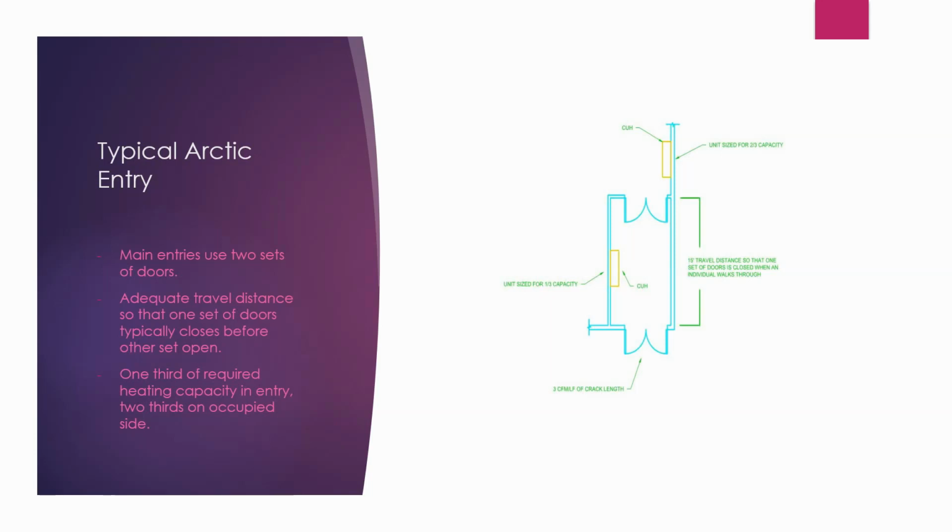So maybe a single row coil with a large cabinet unit heater that cycles significant air. So what you're doing is essentially vacuuming the cold air off the floor and pushing it up, say it's 85-degree air. That air is going to rise to the top, but the fact that you're vacuuming significant air off the floor causes the warm air to be pulled down to the floor.